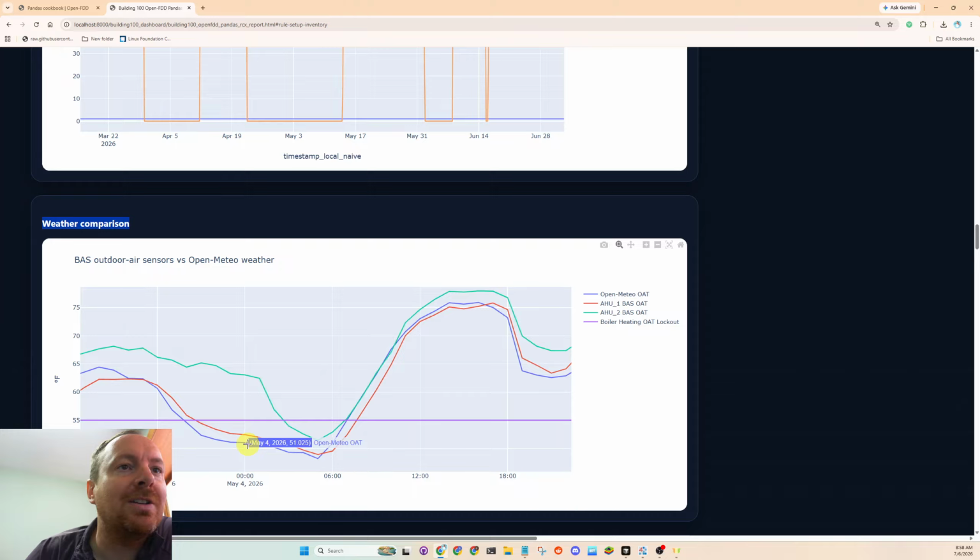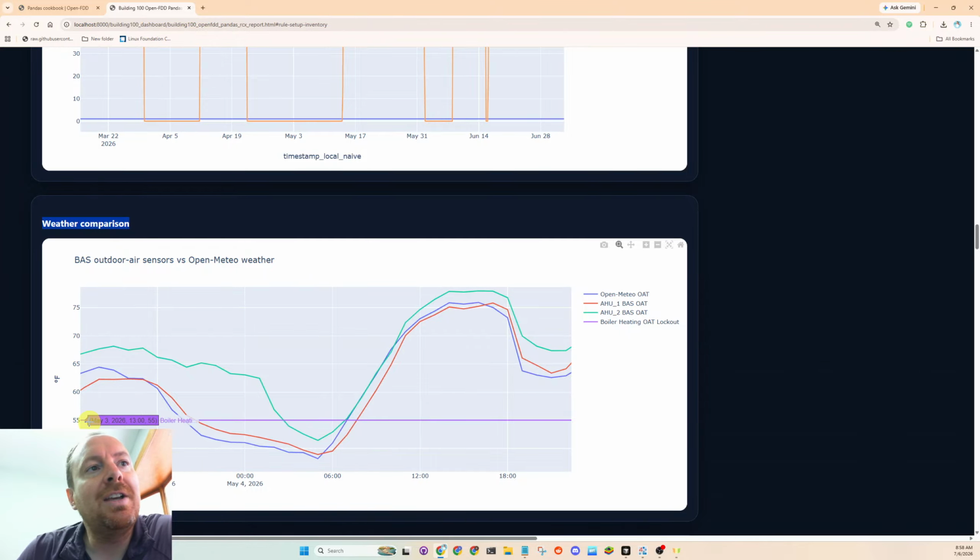So something's wrong here. We could be using economizer free cooling, and the building is running the boiler system right now because this is actually our enable set point to run the boiler system. I'm sure the local building operators may know this too: they may need to artificially inflate the boiler enable set points, as with chillers too, because their local sensors are just off just enough. So what would be a good flag for this?